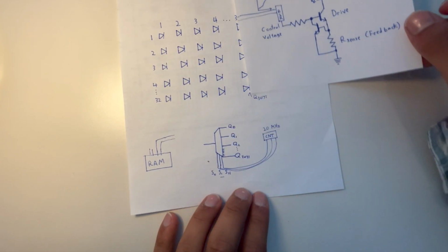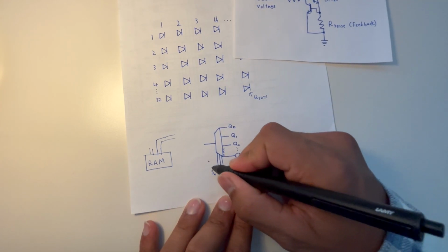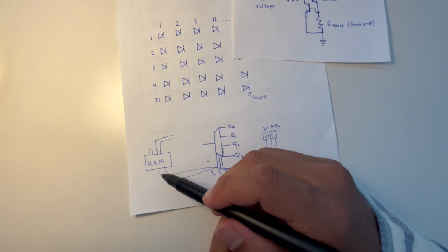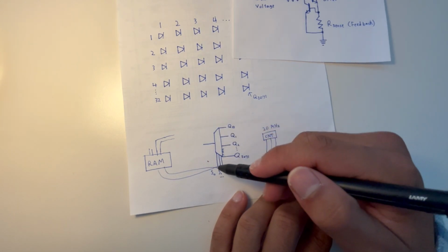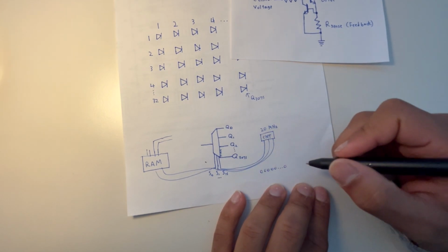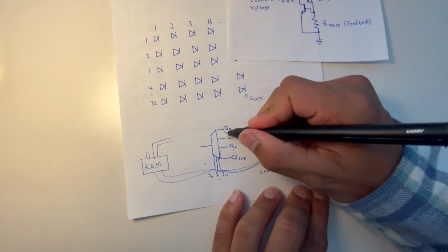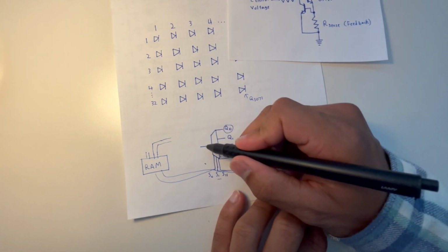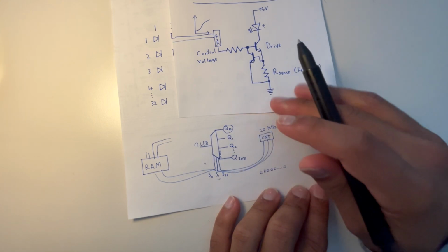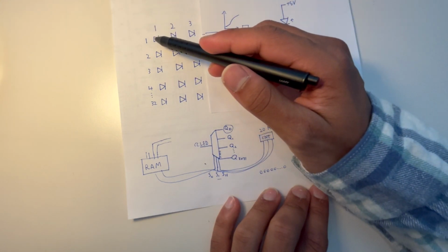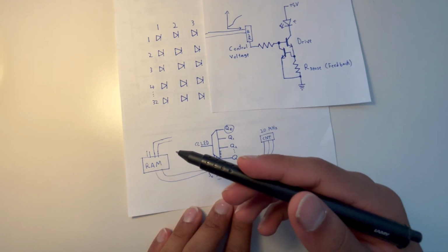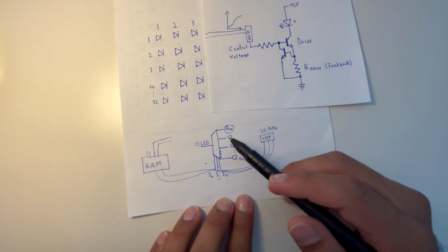Also, the counter is synchronized with the RAM address pins. So that guarantees that the value being read from in memory is going to line up with the desired LED on the demultiplexer. So if the counter outputted all zeros, that would mean that LED 0 is selected. So the input, which is coming from the constant current LED driver, is mapped directly to LED 0, which is there, and at the same time, the address being read from in RAM is address 0, which, as we know from earlier, stores the brightness value for LED 0.